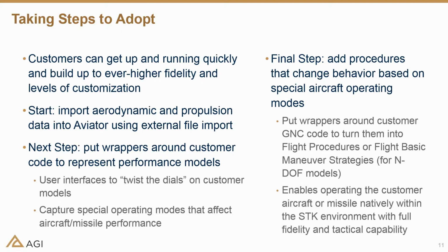The same description I'm applying on the performance side applies to the guidance, navigation, and control aspects, with what we typically call procedures. That's the logic that actually flies the aircraft around to do what it's doing. You can not only make use of our existing building blocks, say build one of your own procedures, plug it in and have that procedure make use of our existing building blocks, or you could take your high fidelity guidance, navigation, and control logic that runs inside your 6DOF sim, put the wrappers around that and fly that inside our framework.